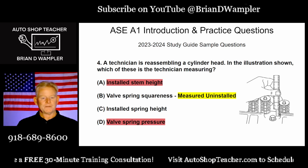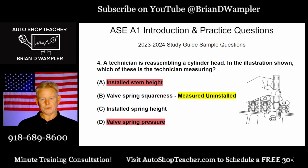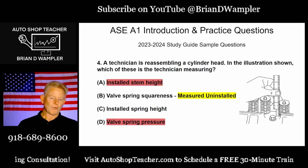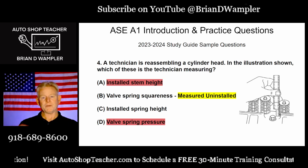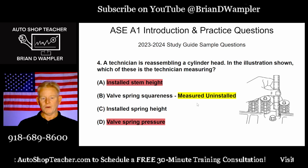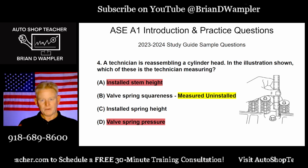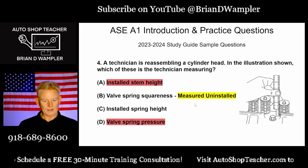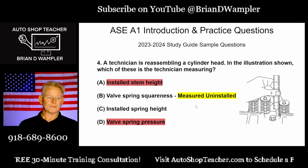This is not a textbook answer, but what we used to do, the first quick test, if we had a good workbench, was just to roll them across the workbench. If they rolled straight, then good chance they were going to pass the test. If you rolled them across the bench and they start going in circles, good chance they weren't very square, that they had become tapered. Keep in mind that measuring the squareness of a valve spring only applies on engines that are supposed to have nice, square, parallel springs. There are tapered valve springs on some engines. So don't think that all engines in all countries for all manufacturers have square coil springs.